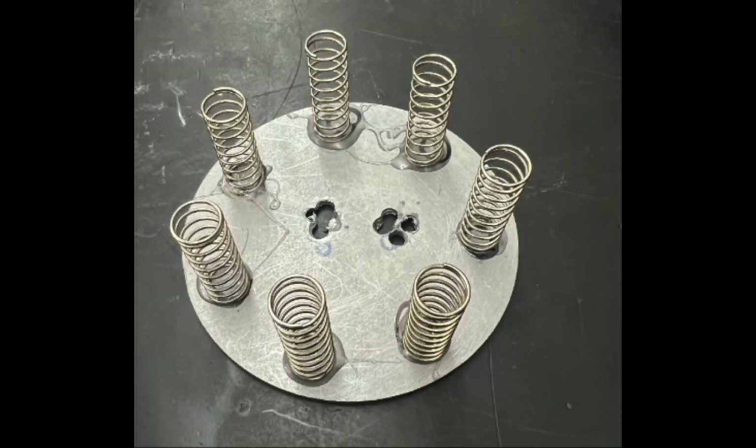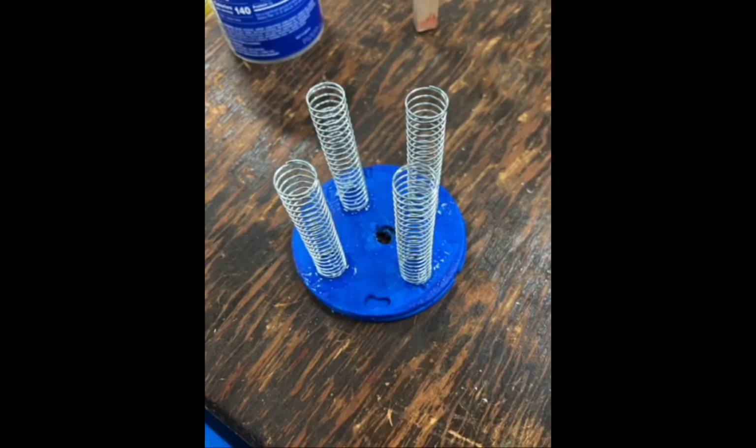For the spring mechanism, this was the first iteration of the spring pancake. We drilled 2 holes in a steel disc for the rope to thread through and glued 7 springs to the periphery. However, this mechanism presented some issues, particularly due to the asymmetric drilling of the holes, excessive stiffness and short length of the spring, as well as the heavy steel disc which would have absorbed energy that should have been used for launching, all of which would have contributed to a dysfunctional launcher.